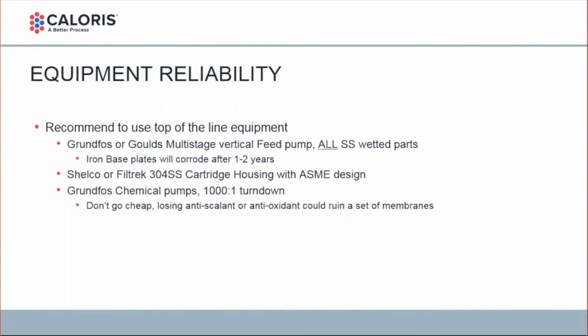Equipment reliability, definitely use top of the line equipment for your feed pump. Use an efficient Grundfos or Goulds multi-stage vertical feed pump. Make sure you use all stainless steel wetted parts. I've seen some iron base plates that typically corrode after 1 to 2 years, and then you've got to replace it already.